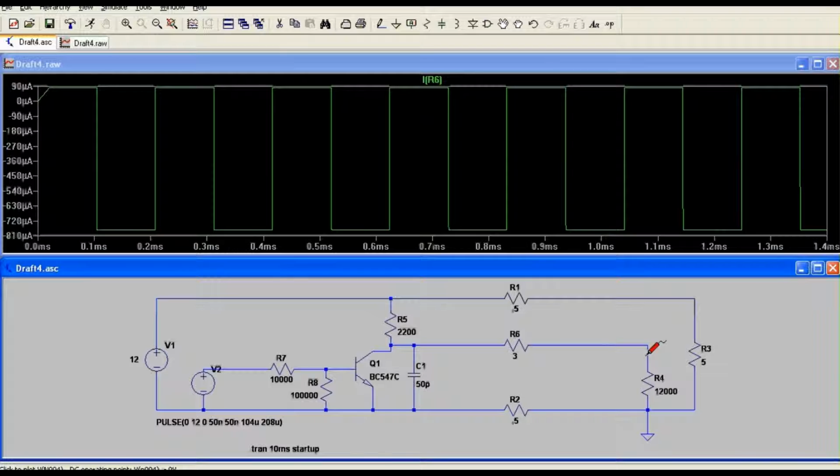And if we can imagine at this end having a multimeter and putting your common probe here and voltage input probe here, because I'm saying there's not a lot of voltage drop happening through there or through the junction of the transistor, I'm saying that it's effectively the same as putting a multimeter here and common here and measuring back across this cable, if you could do that, if that was practical. But in a circuit analysis way, if you think about it that way,